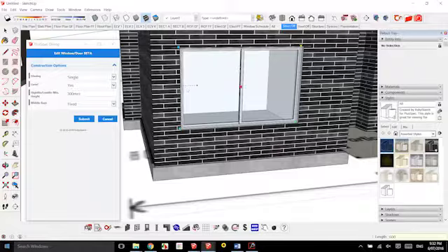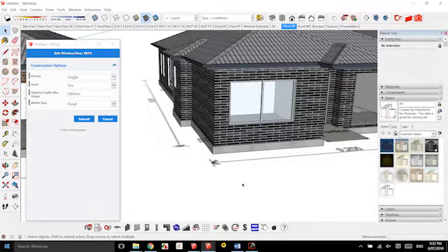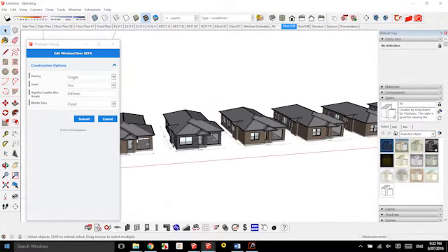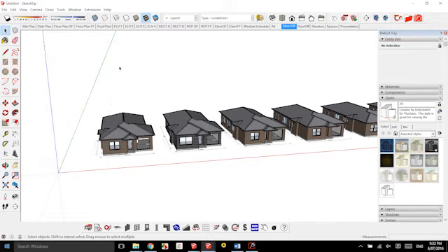Everything is, there's a buzzword you might hear, parametric, which means that one thing can be multiple. We've got a PowerPoint. If you go into PowerPoint, you can put in PowerPoints. A PowerPoint's got 172 different iterations inside one component. If you say I want to put in a PowerPoint with a light switch, a fan switch, a dimmer, it will go through and take that PowerPoint off and tell you you've got one dimmer, one light switch, and these are the item codes so you can order it. Simplifying it was what it was all about.